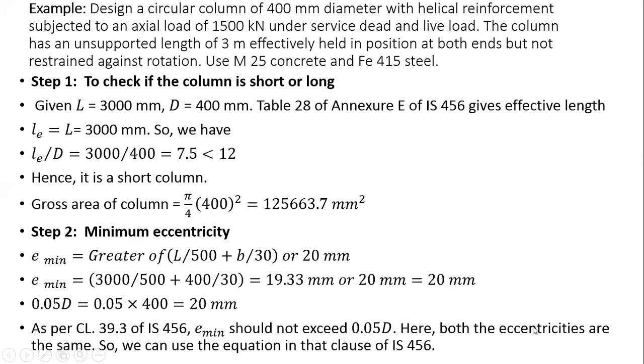Now here both the eccentricities are the same. It should not be more than this value. So this means that we can use the equation in that clause of IS 456 for the design of short columns.